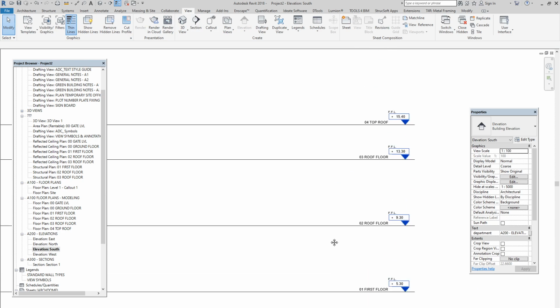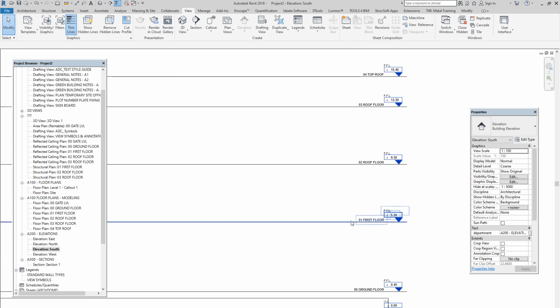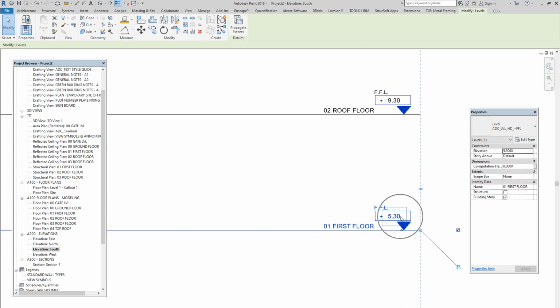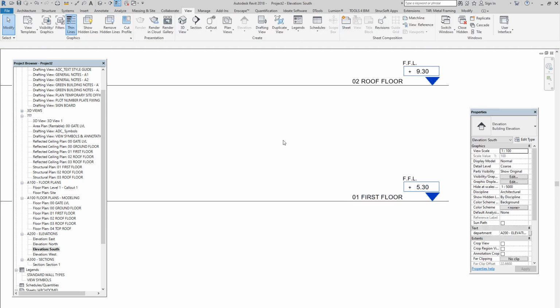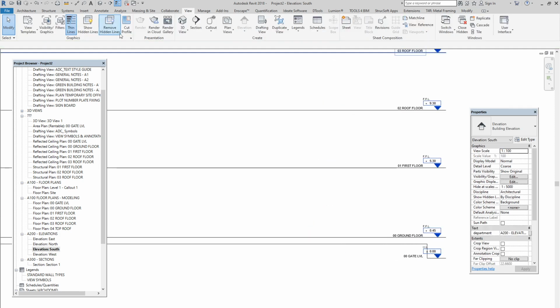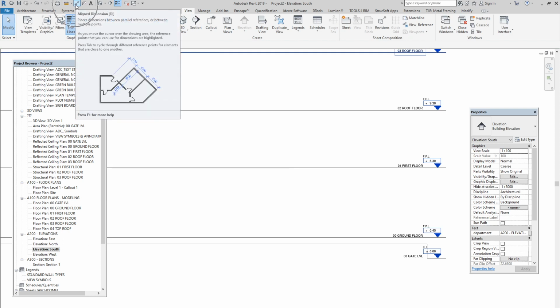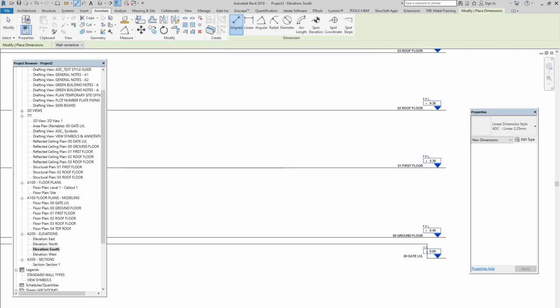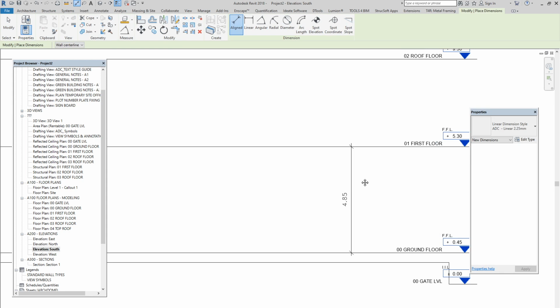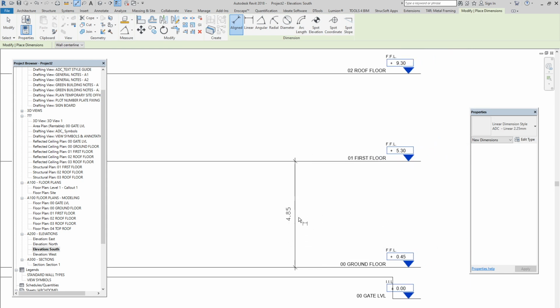Okay, the other parts now, as we agreed, we will use another way. Instead of writing this text here or here, we will use the dimension tool. How will we use this one? Just go to dimension and the shortcut is I. Okay, so from here dimension, and I will tell him pick the dimension from that floor to that floor. Okay, that one is now 4.85.